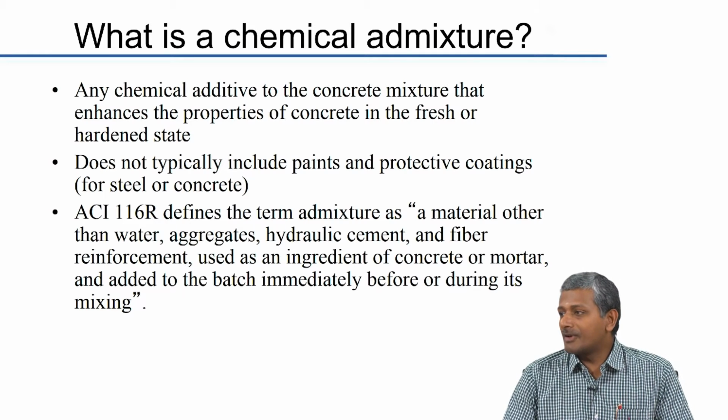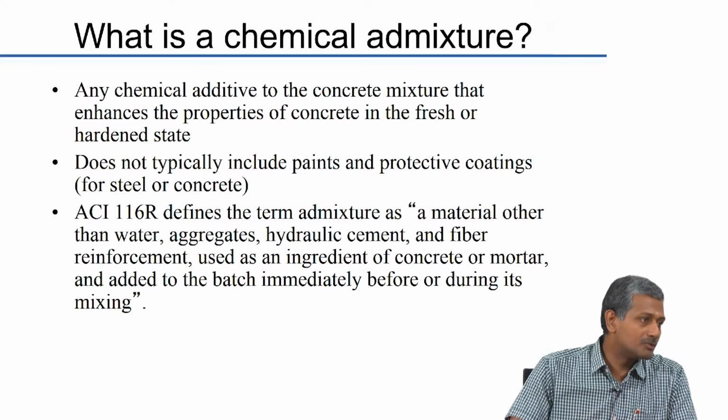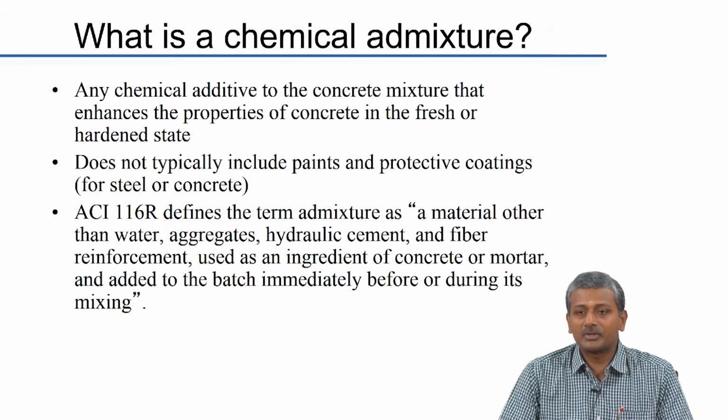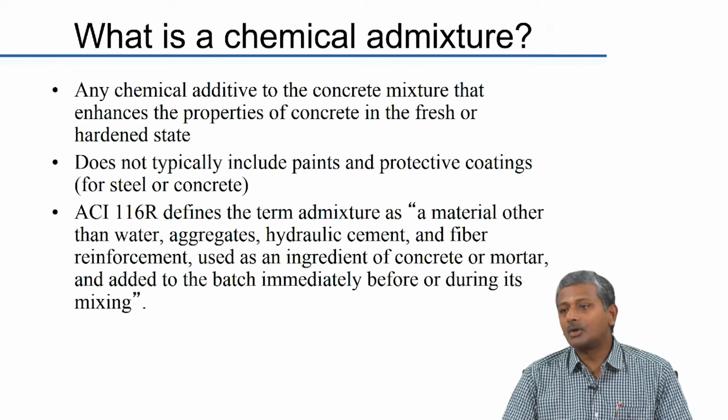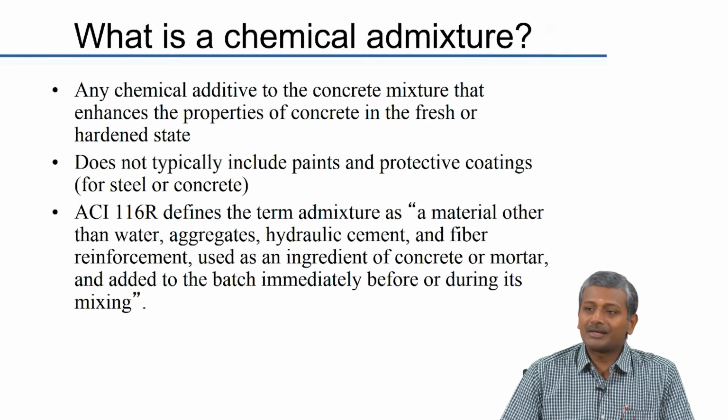But a larger family of construction chemicals also includes protective coatings and paints, which are not covered within the chemical admixtures. So admixture is something which you add integrally to the concrete mixture during the time of mixing, right. So that distinction you need to make.